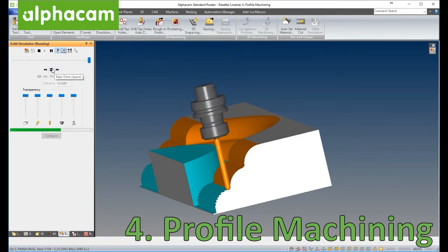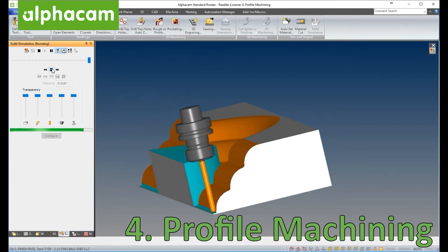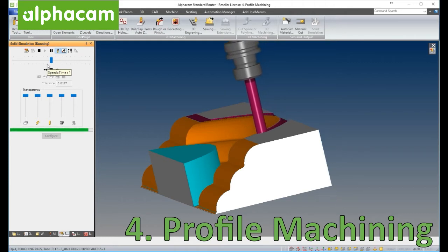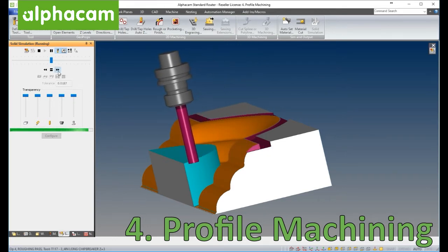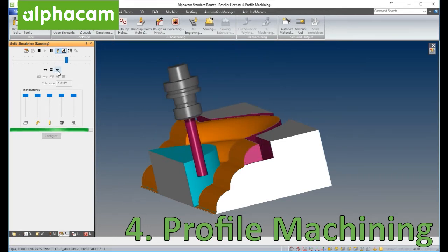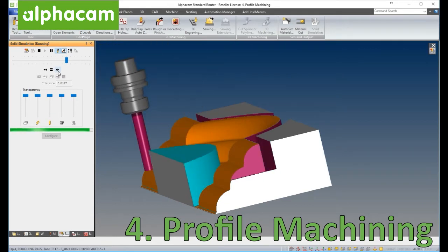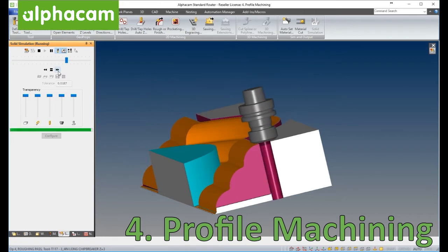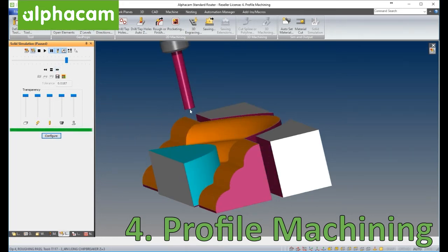The next operation would obviously be taking care of the perimeter of the part, and that's what we're going to do here. So this is a 3/4 inch long finisher. To remind you, 100% of the tools that you're looking at over here are commercially available. And so what I'm doing here is called a helical operation, which is going to continuously go down, right? Helical operation is another advantage of standard router.